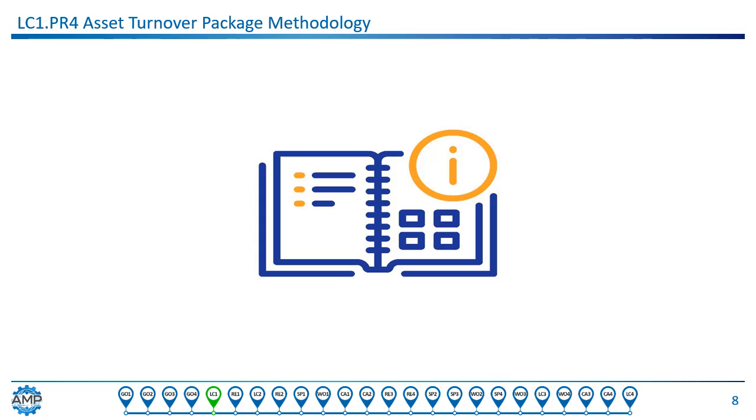Turnover packages should have a specific format that includes things like user and functional requirements, critical process parameters, required spares, technical drawings, technical manuals with recommended maintenance and warranty information, purchase prices. Information in the turnover package is typically provided by the vendor, again emphasizing how important it is for the structure and expected content to be communicated to the vendor before the start of the project.